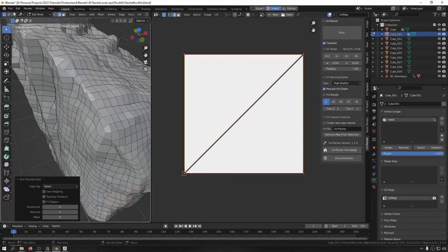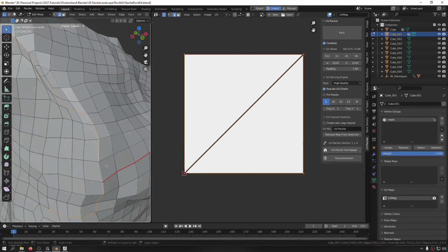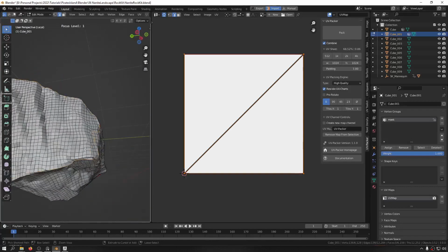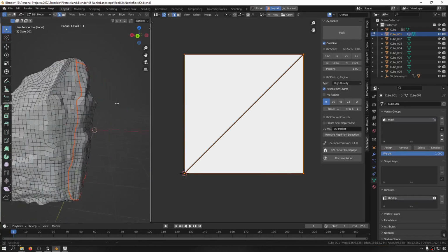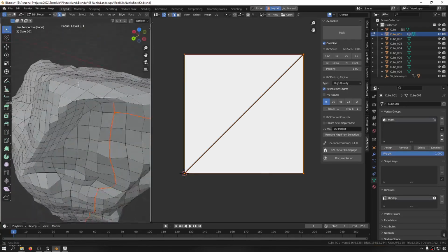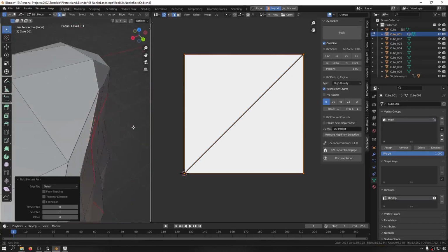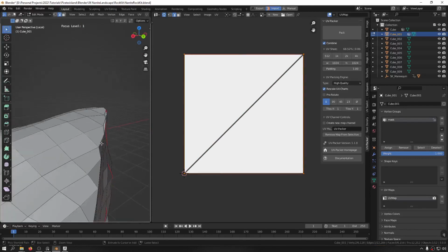And the good thing about these Nanite meshes is that you really do not have to care so much about the lines that you put here. You want something just to resemble the shape. That's all. Okay, mark this one as seam as well. And now let's go for here and make these two also seam so that we can separate this part out.